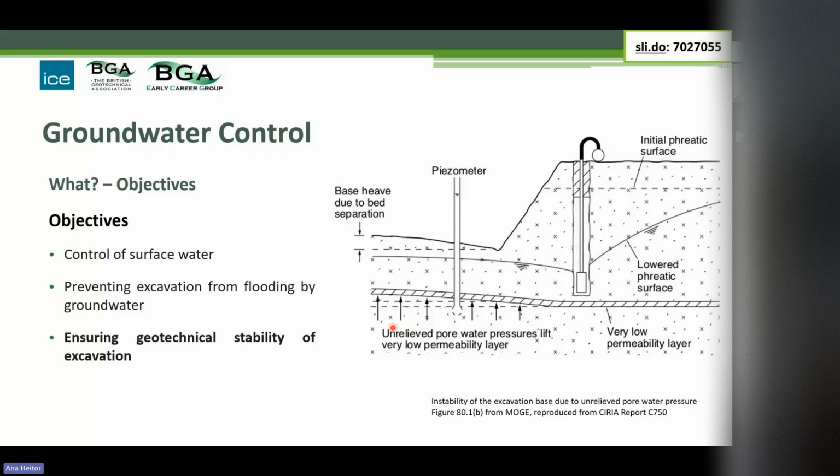So you get the high pore water pressures here in an area where there's low total stress, you get heave, upward movement, and eventually you get what's known as a blow, where you get a rupture and you get uncontrolled water inflow. And again, I would argue that's a failure of the conceptual model, because if the conceptual model identified that this layer was here, they'd either deepen these wells or possibly give it some relief wells.